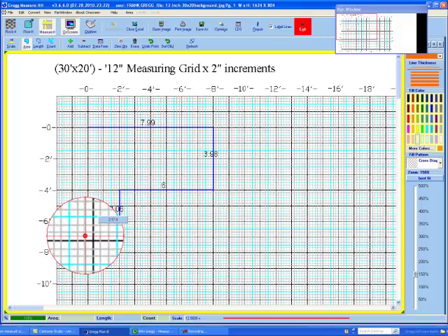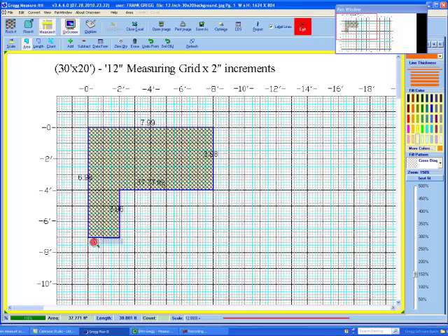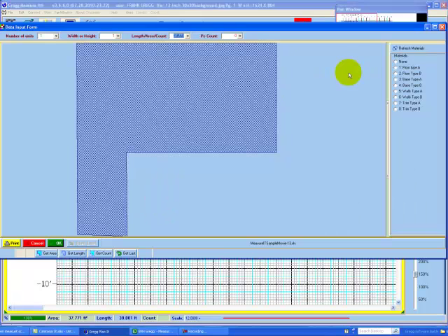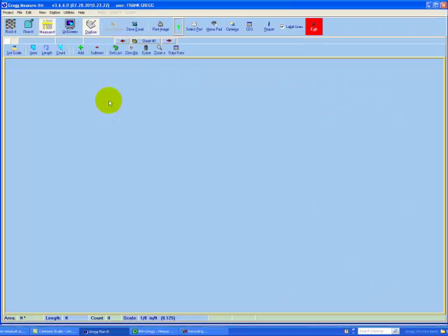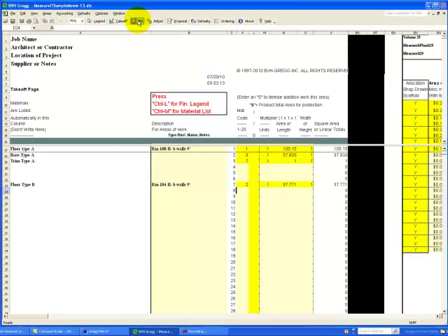Once this area is drawn, I right-click, I hit Add, it draws the area for me, and I'm able to send it into the project just as I did with electronic files. Once the items are drawn, the user can give a price and the drawing approved by the client on the spot. Remember, the Planet program can switch to digitizer mode and do the same measuring functions using paper plans and with a digitizer board. When the takeoff is finished, go back to the bid page summary and start at the top of the bid to complete the project.